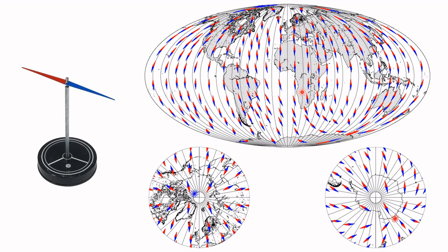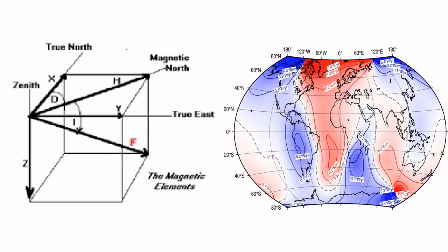Following the same figure, in which the magnetic meridian is the vertical plane passing through the total magnetic force, F, the declination, D, and the inclination, I, completely define the magnetic field at any point on the Earth. The total force vector, F, of the Earth's magnetic field can be resolved into vertical, V, and horizontal, H, components. The horizontal magnetic force, H, can further be resolved into X and Y components in the direction of the geographic meridian and its orthogonal component. H is always considered positive whatever its direction, while V is reckoned positive downwards, having the same sign convention as I. The X component is positive if northwards and Y positive if eastward.